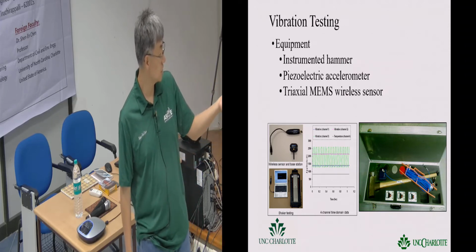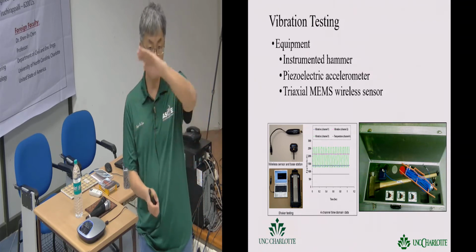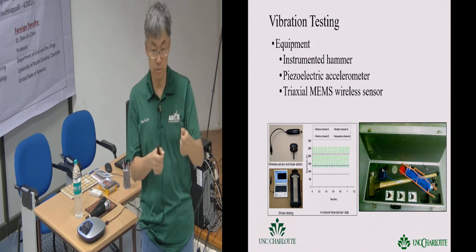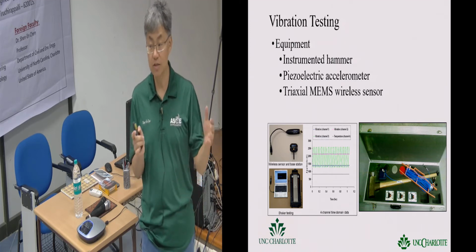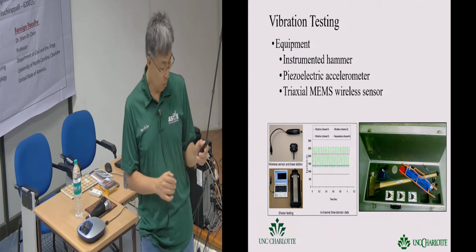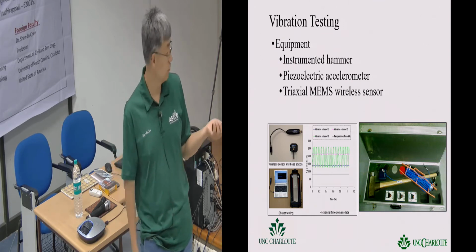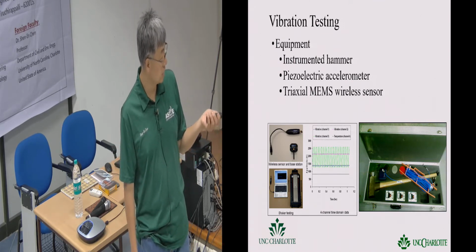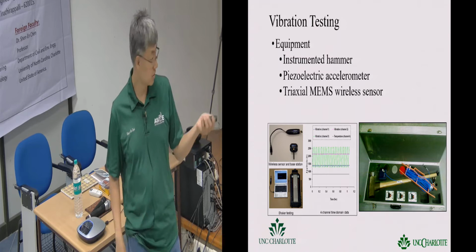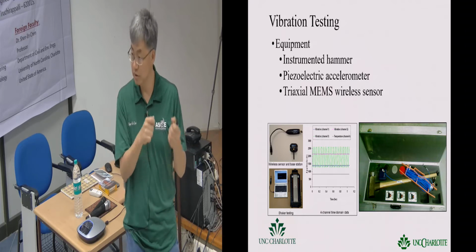And this is what I was discussing, an impact hammer. When an impact hammer hits the ground, it actually generates a broad band of multiple modes. And all the energy is limited by the force that you apply. So it is a very stable method for excitation. However, the processing of the data becomes very complicated. And when you use any of those instruments, especially the traditional instruments, you have to be careful because it usually has a power supply. So those are the gauges here. You have to make sure there is always sufficient energy input into your hammer.